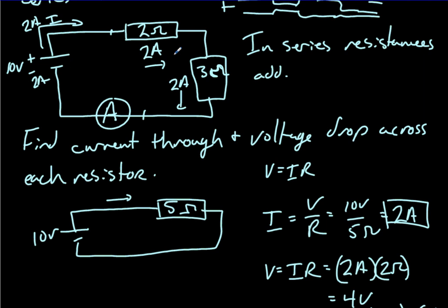So if you imagine, we look at this circuit diagram, you've got a 2 ohm, say, light bulb plugged in, and you've got a 3 ohm light bulb plugged in series on the bottom branch there. Okay, you with me? When I flick the switch and allow charge to start flowing, the circuit experiences these as adding up to 5 ohms total. If we know potential, we know resistance, well, I equals V over R. We have 10 volts total divided by 5 ohms because this is equivalent to being 5 ohms. You'll have 2 amps flowing in this circuit.